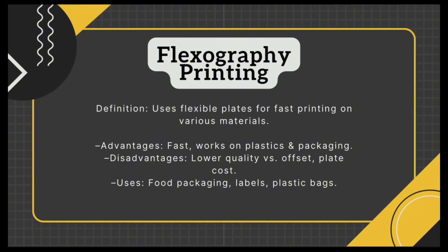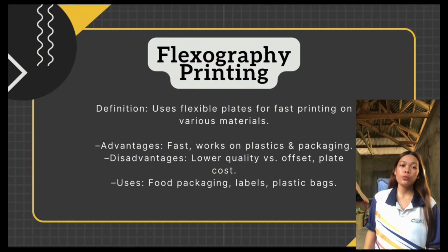Flexography printing. Definition: uses flexible plates for fast printing on various materials. Advantages: fast, works on plastics and packaging. Disadvantage: lower quality versus offset, and plate cost. Uses: food packaging, labels, and plastic bags. It is often called flexo.